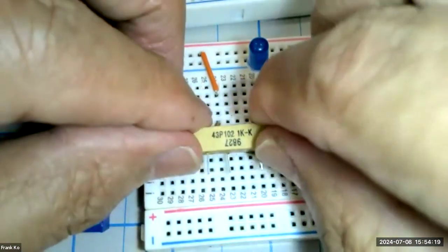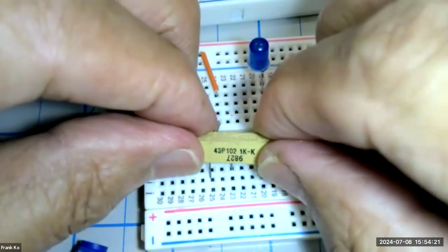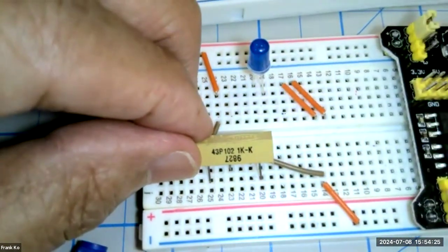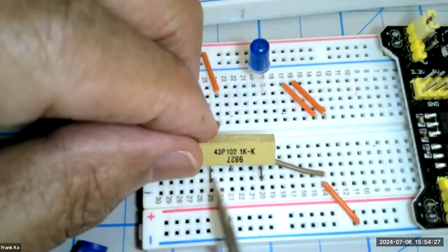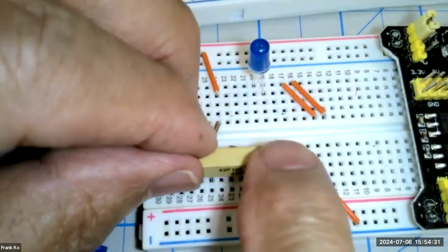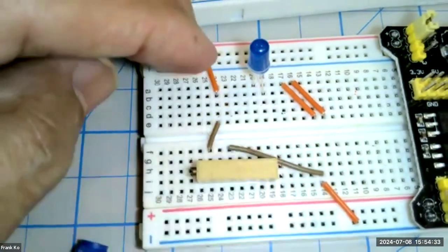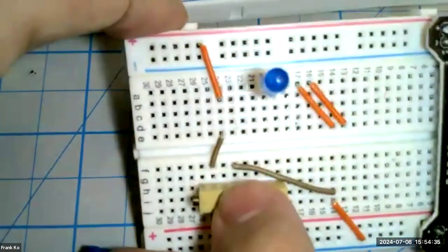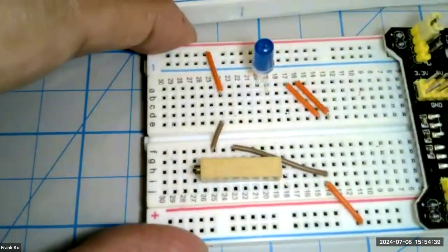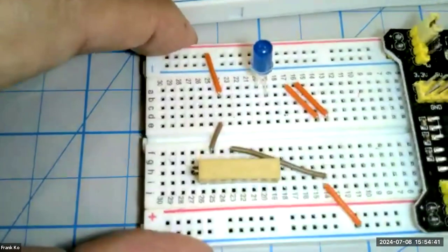So I very carefully look on the board and find a convenient place for this to slip down into. So is my outside pin on row 25? Is my middle pin on row 23? It is. Line it up carefully, push down like so. And now this is on the board and making continuity with the rest of the circuitry.